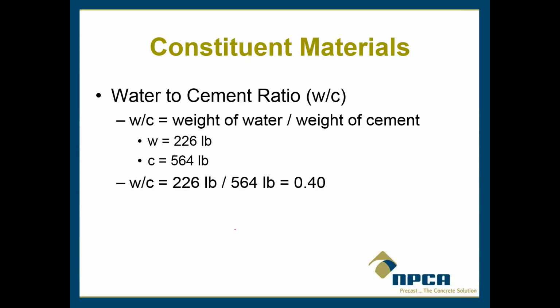So a water to cement ratio between 0.40 and 0.45 is what's really required for proper cement hydration. If you have a water to cement ratio greater than that, so 0.6, 0.7, something crazy like that, when you have just excessive amounts of water, that water remains in the concrete matrix. There's no more cement left to hydrate with that water. All the cement has reacted. There's nothing left. So that water stays in the matrix, and eventually it'll evaporate and just leave these void spaces. And void spaces, just air, has no strength at all to it. So that really detrimentally affects the long-term strength of your concrete.